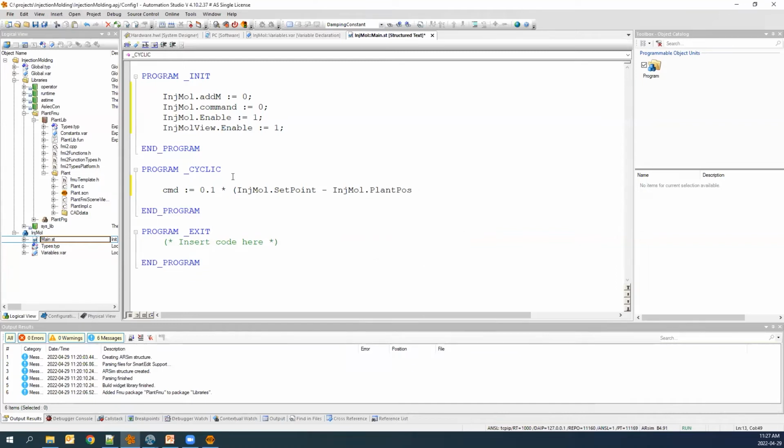There we go. And you can see from here how, normally in your PLC, you might be pulling data from a reference that is an actual machine, and all you would need to do is really substitute that with pulling the same data from your digital version. And so by doing this, you can really make the transition between having a communication between your physical machines and your virtual one kind of one-to-one.